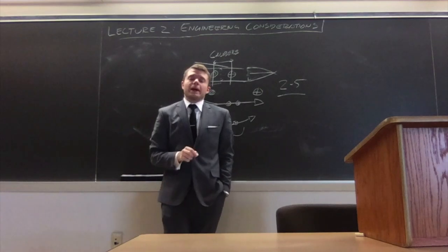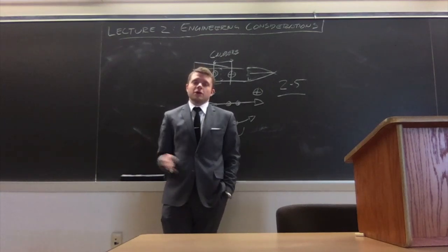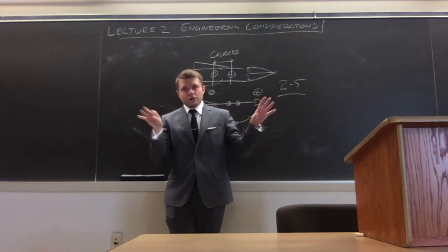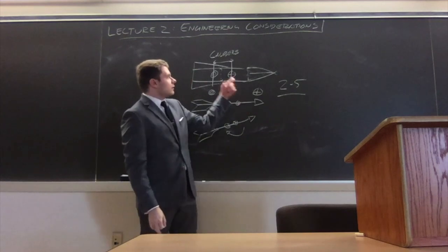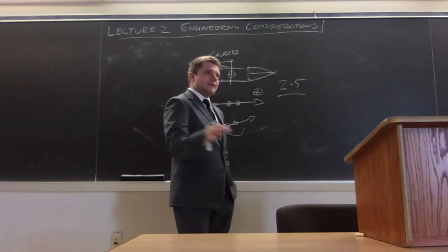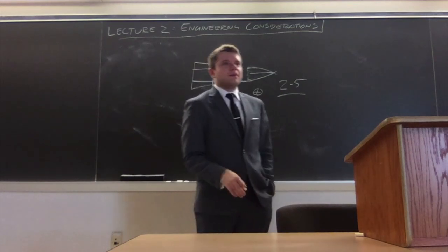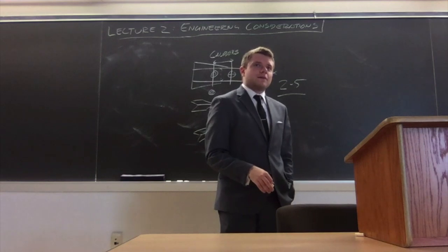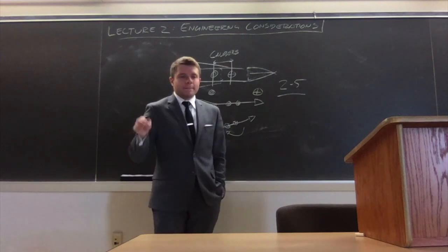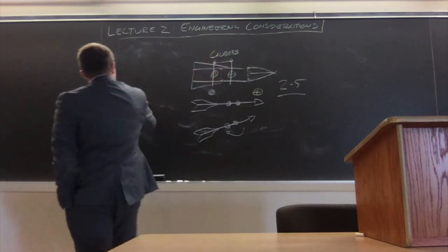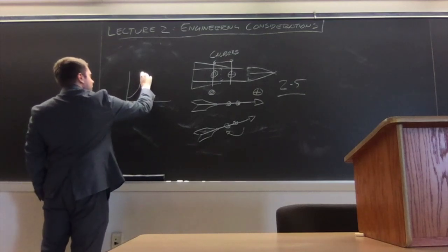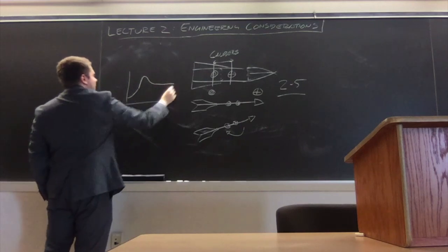Fortunately, we don't have to do this by hand because there are programs that will do this for you, such as OpenRocket, which is a Java-based 6-degree-of-freedom simulator that you can actually put together a little silhouette of a rocket in, and it'll calculate for you your center of gravity and your center of pressure. Very nice, sweet, simple, pretty handy. But, of course, with anything, something so simple is not truly that simple because there are caveats. There are major caveats. And one of the most major caveats to this is going past Mach 1. If you're familiar with drag and how it behaves at very high speeds, you might recognize that the coefficient of drag will go up, basically uptick right around Mach 1 and then kind of level off at some constant beyond that point.